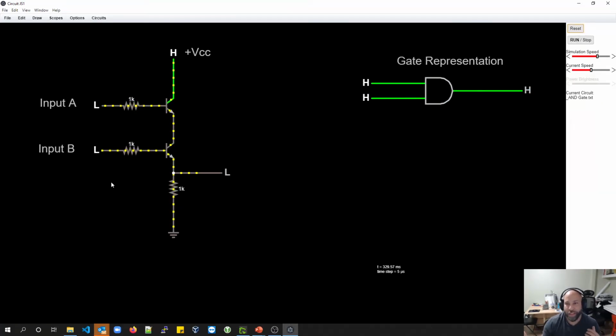So now that we've abstracted away the representation of the transistors, let's bring it back really quickly. So we have our voltage being presented here, and we have an input going into the base. And you can see how the emitter from the first transistor feeds into the collector from the second. If I were to put a logical high, sure, voltage passes through the first transistor, but it stops right here. There's nothing coming out on this output right here. But if I turn this other input, this other base, high, controlling this transistor as we talked about that we can, you can see that now I'm able to get a logical high or a voltage high. Or in the language of computers, I would be getting a 1 out, right? I've added two voltage highs and I'm getting a 1 out. That is an AND gate for you.